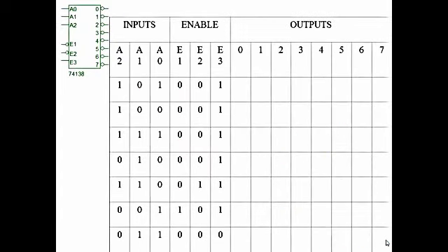Okay, this one is a decoder, and it actually decodes a binary number, which in this case is an octal number, over to a decimal number. So you see again, we have our inputs A0, 1, and 2. Those are our binary inputs, 1, 2, and 4.